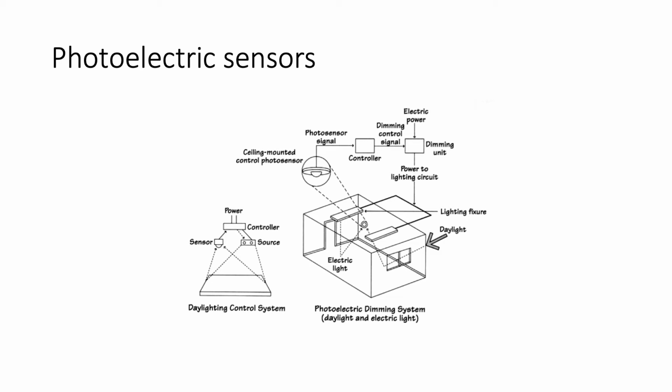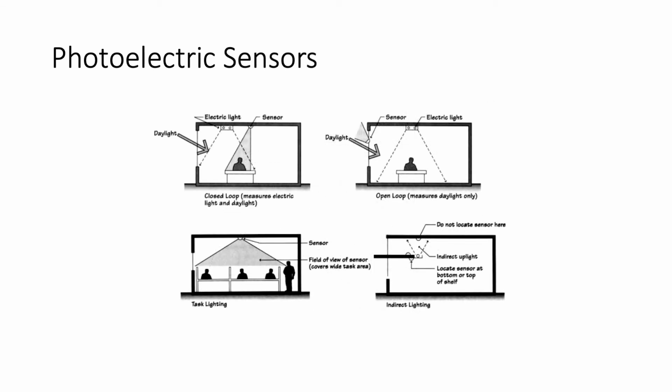As mentioned in the daylighting lecture, you can use photoelectric sensors. The placement of these sensors is actually a real science, because exactly where they are and exactly when they cause lights to go on or off or dim is quite complicated. And those photoelectric sensors combined with motion sensors are not cheap. You also want to make sure they are placed where the task is occurring.